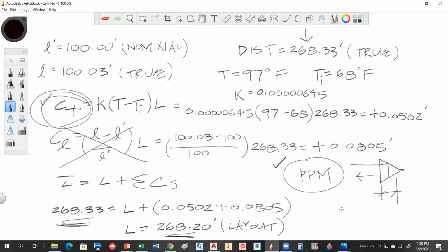So they typically use 0 millimeter, which means this guy's pushed just where it needs to be. One of the common ones they use is 30 millimeter offsets, and that can be either a plus 30 millimeter offset or a negative. So you enter this number into the total station, and it adjusts your distances accordingly to what your true correction should be. But let me tell you, this can be a problem.